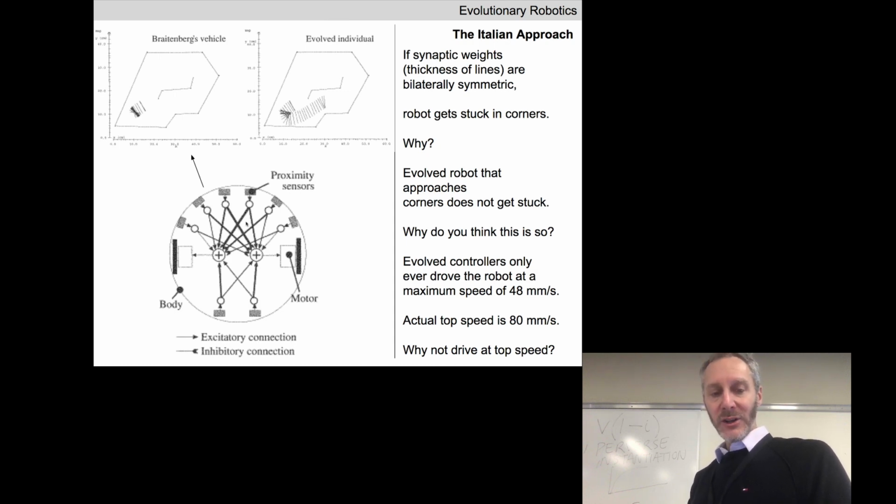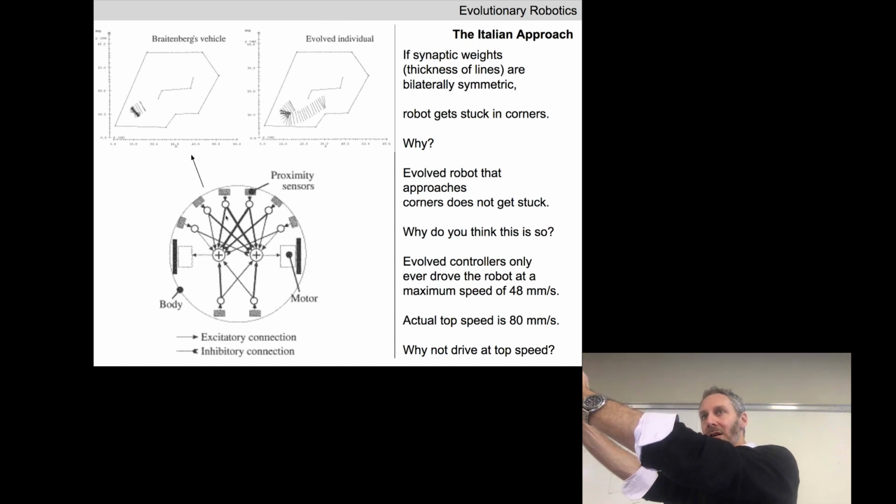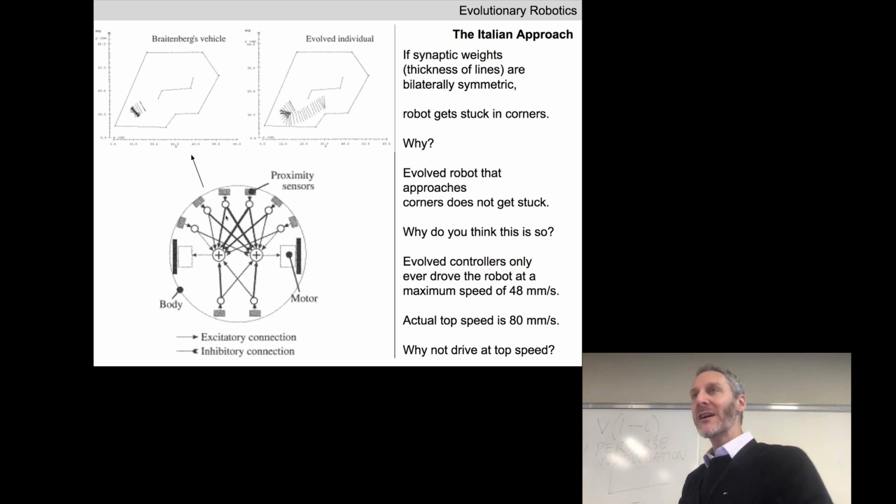So if you look carefully, you'll notice the widths of the synapses. Some of them are broader than others, which tell you the weights are stronger. So if we look at, for example, the left motor neuron here, it's receiving values. There should be 8 incoming arrows. The incoming arrows that are more anterior, closer to the front of the robot, are thicker, meaning they have stronger weight, and the ones at the back slightly less.